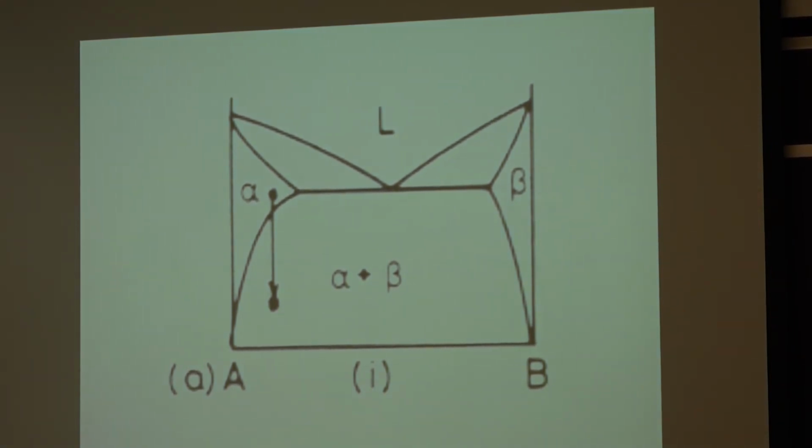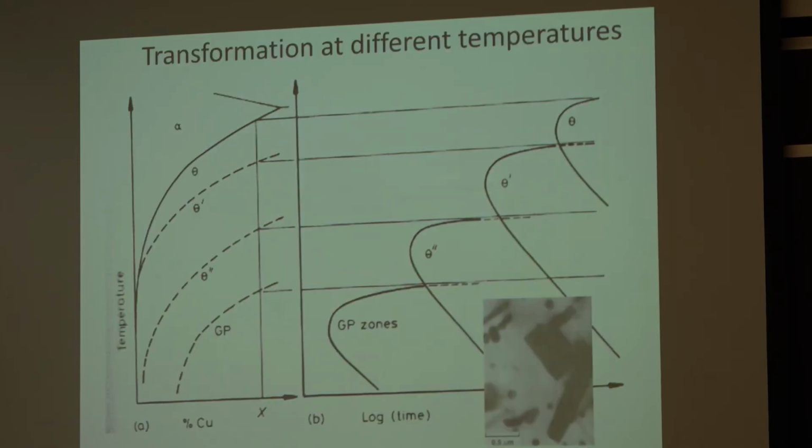This is a phase diagram, and if you take aluminum, a lot of times aluminum for airplanes is essentially heated to the point where it's in solid solution, so there's only one type of crystal in the microstructure, and it's cooled off where it wants to transform into 2 phases. Now, depending on your cooling rate and the temperature that the transformation is taking place, you're going to form large precipitates, that's the high temperature case, or very, very fine precipitate, that's the low temperature case.